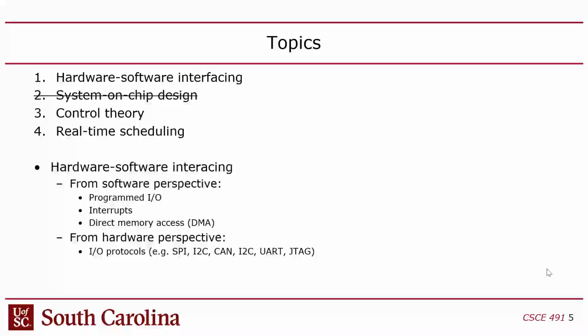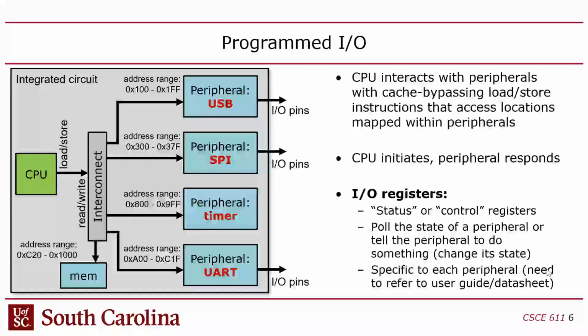Driving a protocol directly from software is a very inefficient use of the CPU, which is why these embedded chips have hardware to do that. But bit banging serves as a valuable educational tool so you can learn how the protocol works. You guys with me? It's not very practical, but it's good from an educational sense, especially when we don't have SystemVerilog and FPGAs and you can't actually implement the hardware.